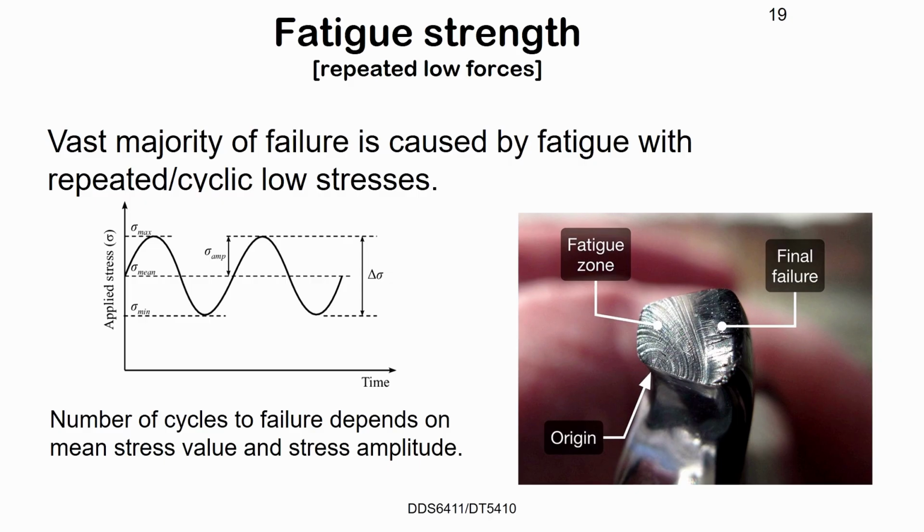In theory, the number of cycles to failure depends on the mean stress, because you can have tensile, then compressive, tensile, compressive, or you can have purely tensile, even though it's still repeating with changing magnitude. The higher that mean stress, the lower the number of cycles required to break something.